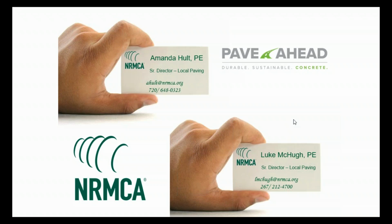So the first question that we have is, why can't the exterior pavement design be used for the interior slab? A lot of times interior slabs are more of a structural slab. If they're built into the structure itself, you have to deal with it separately. An exterior pavement takes into consideration the traffic.